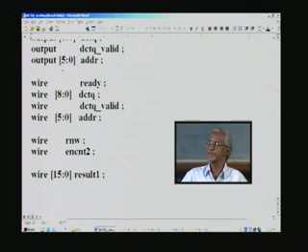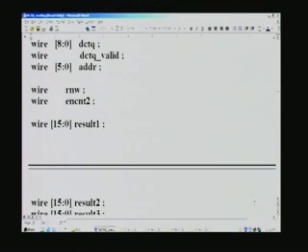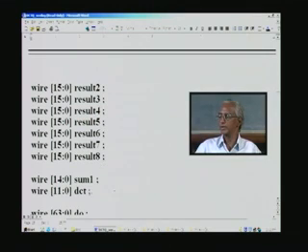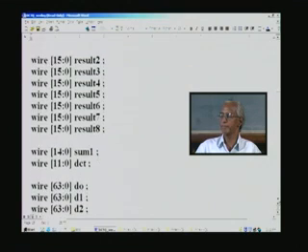For example, address is 6 bits here, and DCT-Q is 9 bits, and DCT will be 12 bits, and so on. And if you remember the first CX multiplication, we used 8 multipliers. They all produce the outputs result 1 through result 8, which are 16 bits in width and are listed here, and finally we added all of these in order to create one partial sum, and that is